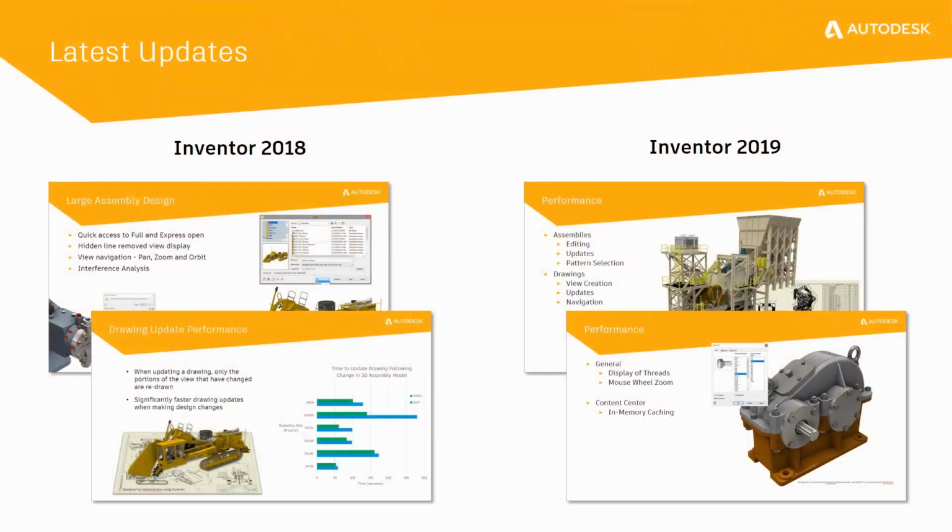One thing we really haven't mentioned in all of this series is the relevance of using some of the more recent updates of Inventor. It's not uncommon to go out there and find a company that is standardized on using 2, 3, or possibly even older versions of Inventor. But what I would recommend is if you're encountering large assembly performance issues, look to some of the newer versions.